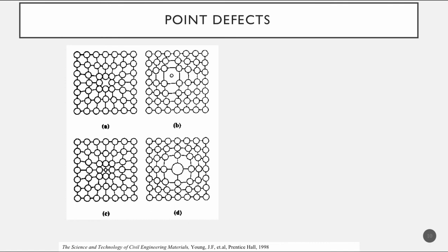C and D are both what are considered interstitial atoms. So again, a different material, so maybe a smaller or a larger size atom, joins in to your actual lattice and starts to become an atom inside one of your unit cells, but it again changes the form of the lattice, and that can inhibit the slip.